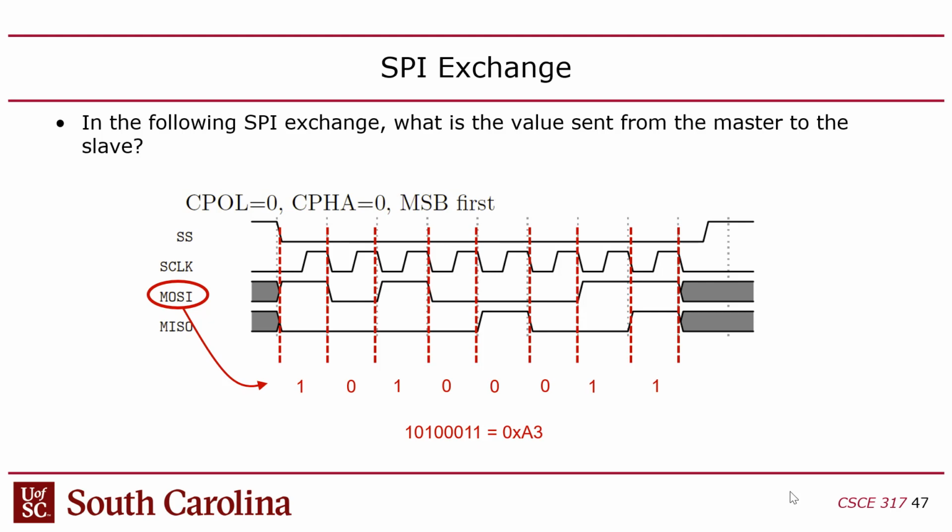But more importantly, you're going to be more susceptible to errors because you're going to have a disagreement about when the data is being read. If you've got a disagreement there, you could have one side of the channel deliberately trying to drive its data or change the state of the bits on the same edge of the clock that the other side is trying to read, right?